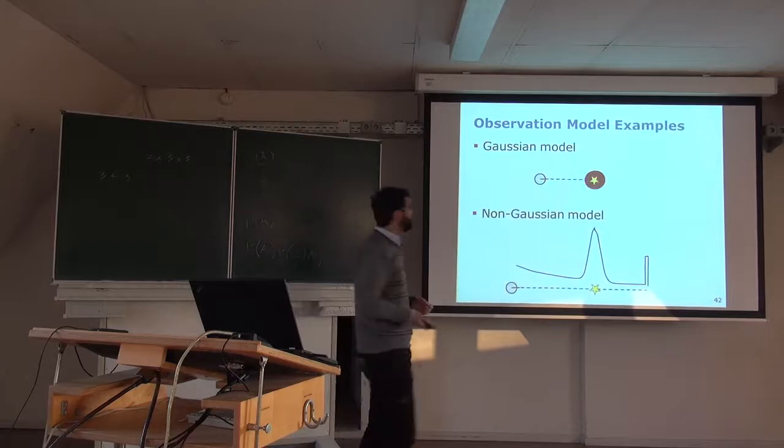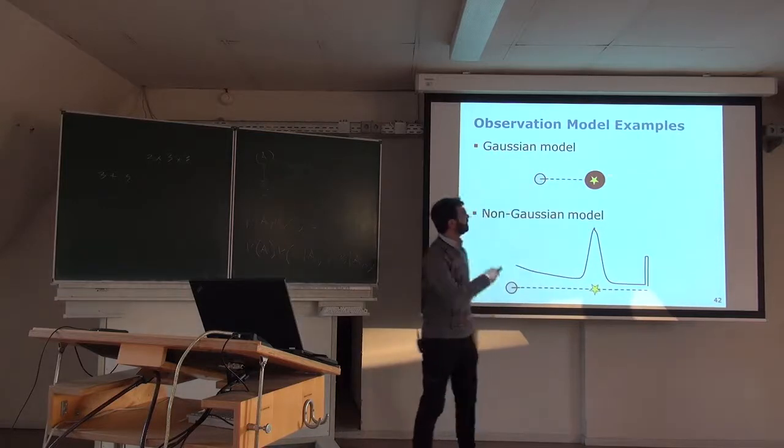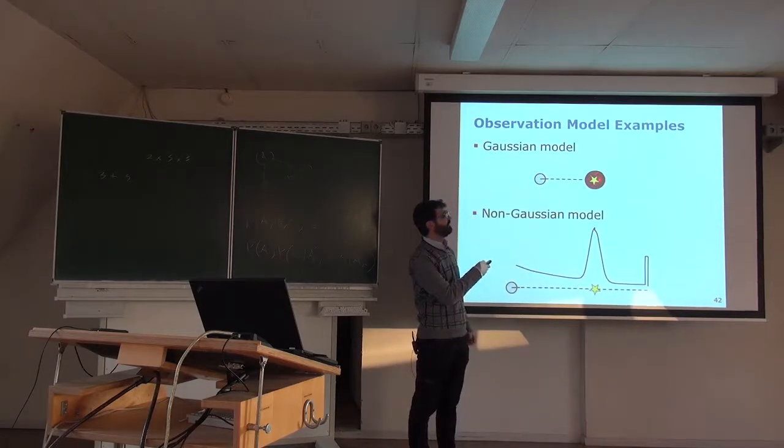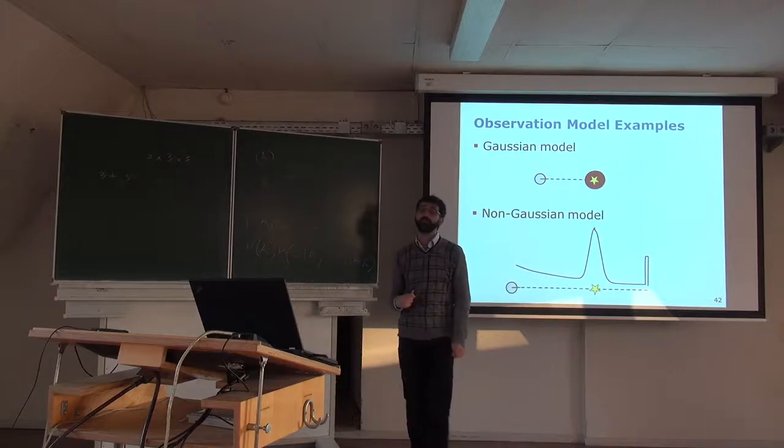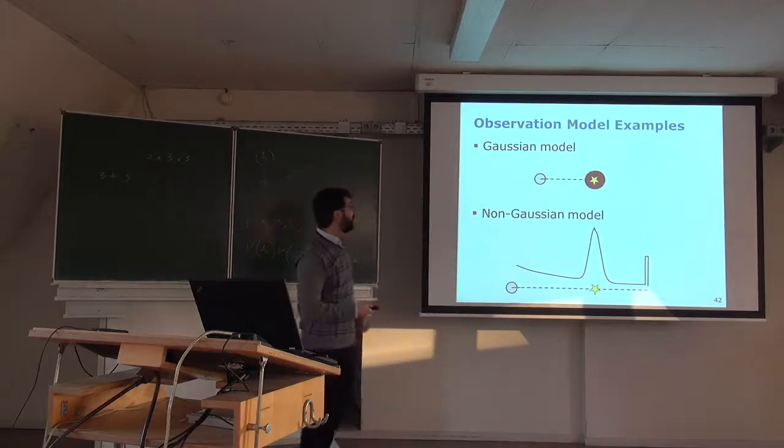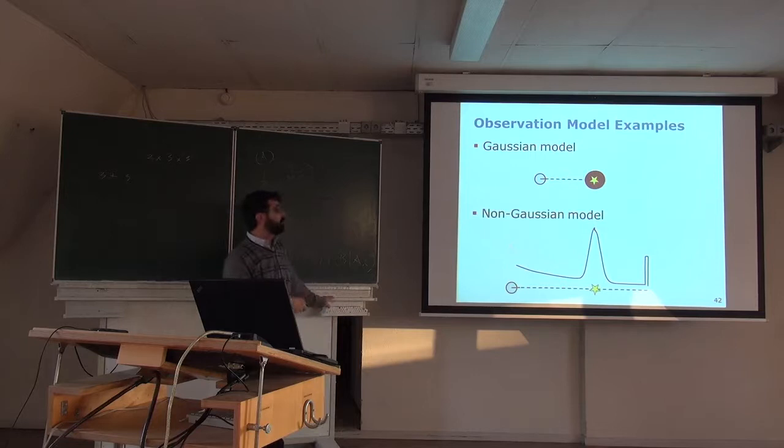You can imagine again to have Gaussian models. So I know this star is my map. Here is my pose, and I know that I have a certain mean distance, maybe mean angle, and a certain uncertainty around that. Okay, so that's how I can represent it. Or I can also represent it in a more sophisticated way with this mixture distribution that is made of different elements.